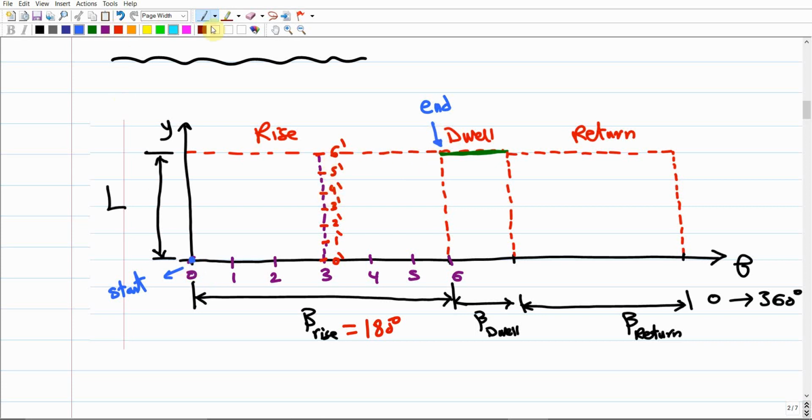So we are going to connect the start point. Let me use this color. This start point with the 0 dash, and the start point with the 1 dash, the start point with the 2 dash, the start point with the 3 dash. Make sense? So the first 3 or 4 marks will be connected to the start point, and starting from 3 dash you are also going to connect to the end point, including the 3 dash. Why 3 dash? Because the 3 line is the middle mark. So you are just going to connect this middle mark to the end. If your drawing is accurate, this line should be a straight line all the way from the end to the start.